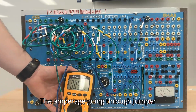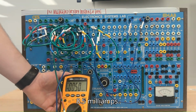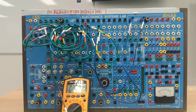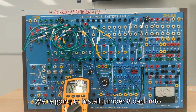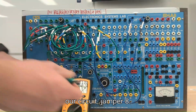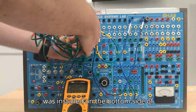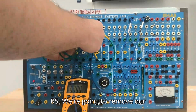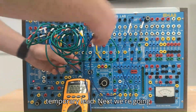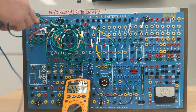The amperage going through jumper 8: 5 milliamps. We're going to install jumper 8 back into our circuit. Jumper 8 was installed on the bottom side of R5. We're going to remove our temporary lead. Next, we're going to move on to J9.